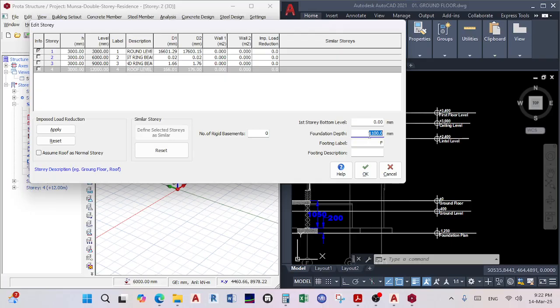In some instances, you might actually find an aquifer or a water table. But even if you find a lot of rock, you can always level it, and it's best if a structure is resting on rock, because it rids you of things such as differential settlements. So here I just want my foundation to be deeper. I would like a total of, I'll say maybe 1,200 at the top of my footing, and then a 300 thickness base will give me a total of 1.5. And that's usually standard, right?